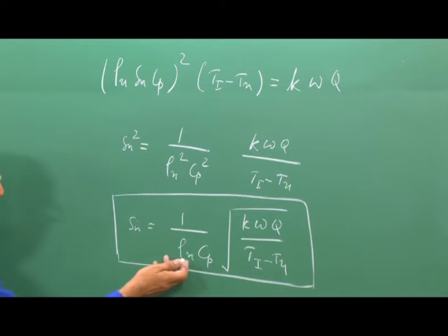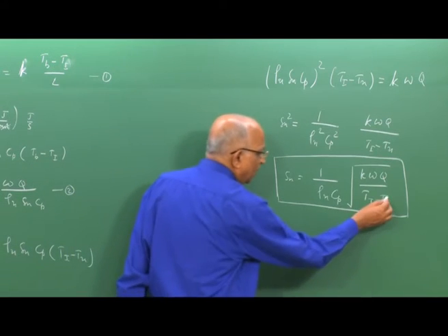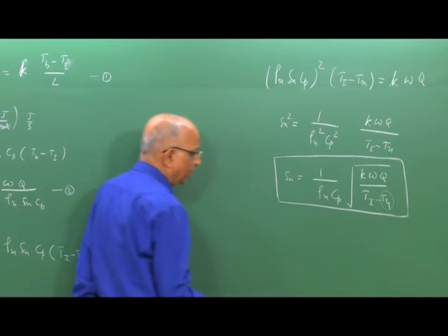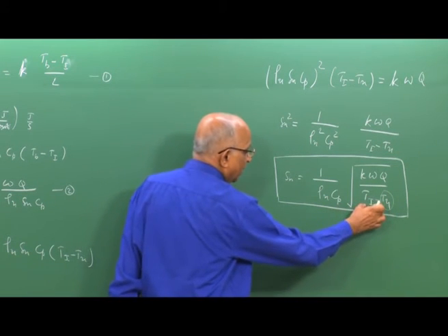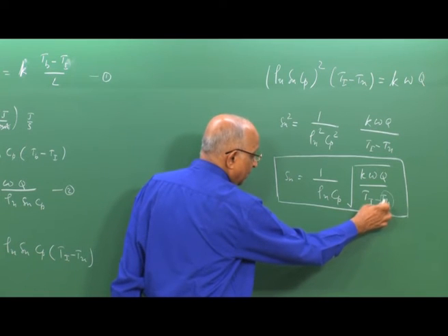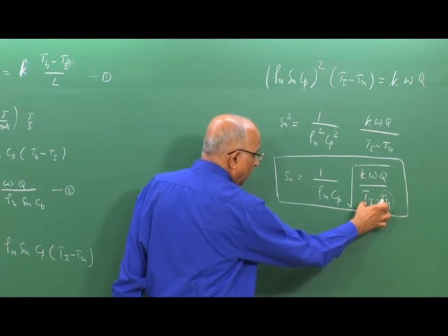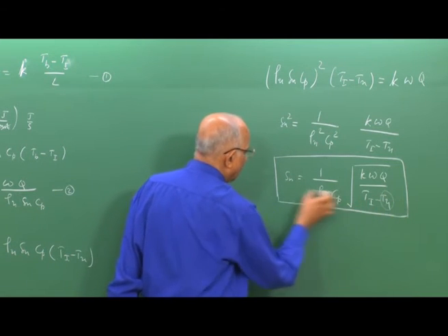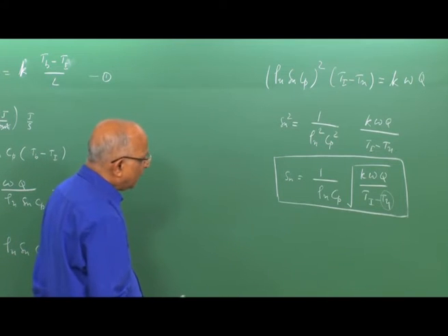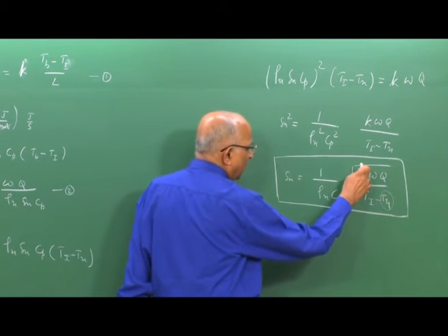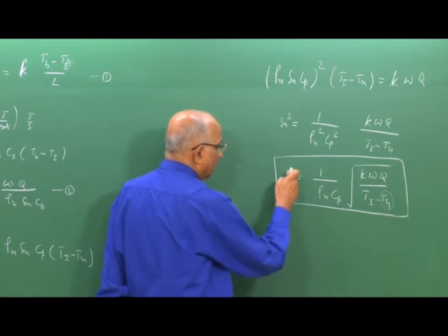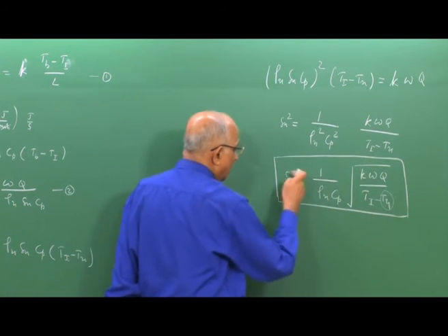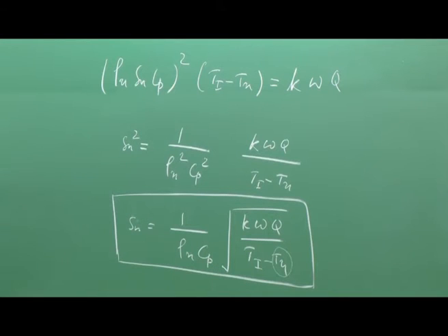We say, well, as the density of the unburned gas mixture decreases, the flame speed increases, point 1. We also say if the unburned gas mixture is at a higher temperature, well, the denominator decreases here. The denominator decreases by a higher quantity, and therefore, when the unburned gas temperature is higher, the flame speed is higher. But can I put it in terms of reaction rate? Well, I find yes, if the thermal conductivity is higher, the flame speed is higher. If the heat release is higher, the flame speed is higher. Can I put it in terms of omega?